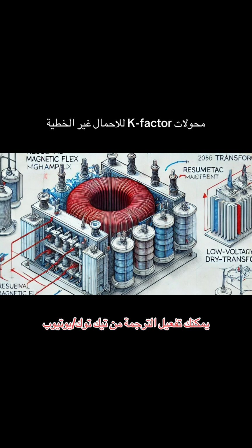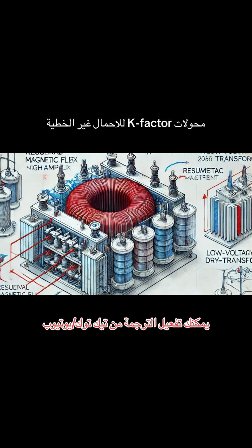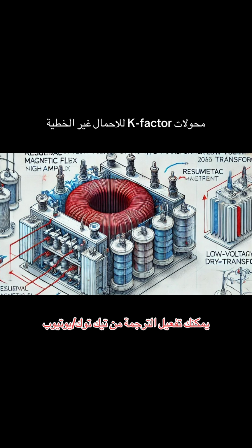You got it. All these little tweaks, they all contribute to the transformer's ability to shed that extra heat generated by the harmonic currents. It's important to remember that these transformers don't eliminate the harmonics. They're built to withstand them, to keep going strong in the face of this hidden electrical stress. Right, they're like the heavy-duty workhorses of the transformer world.